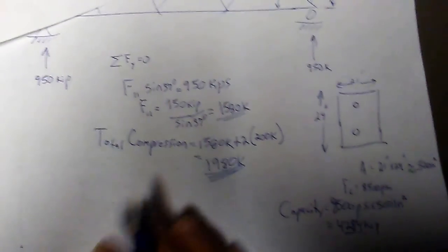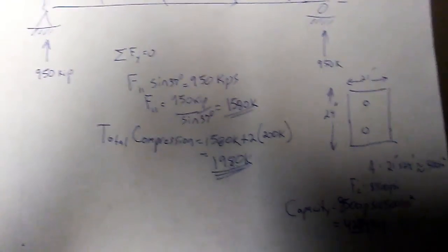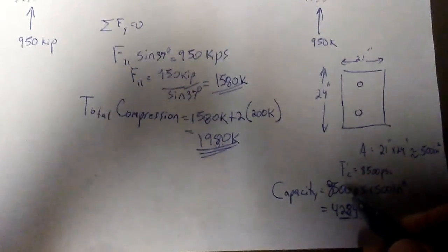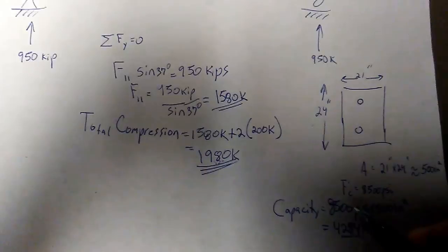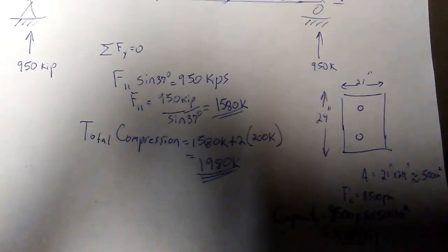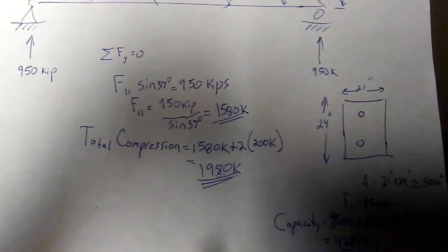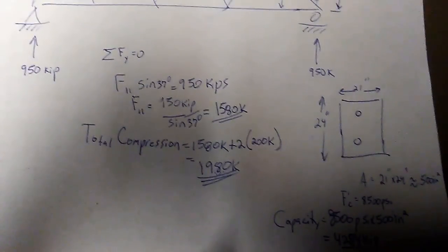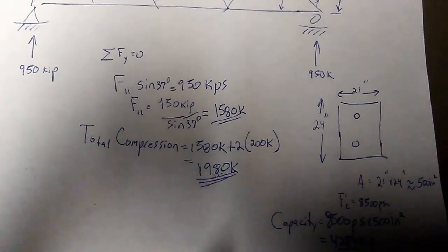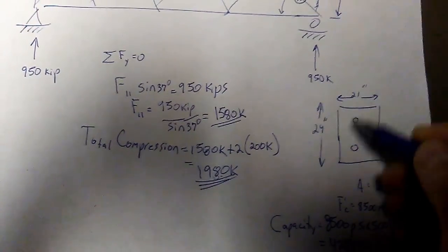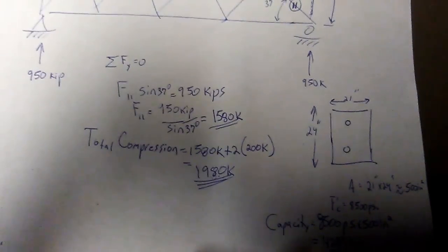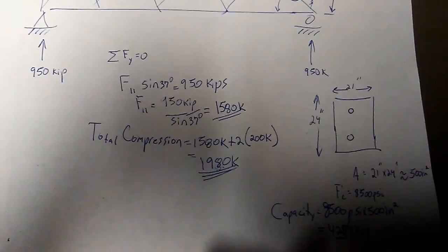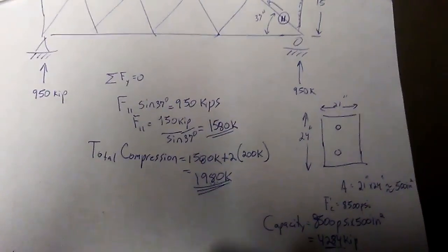There's a factor of safety for the concrete. You actually reduce the strength of the concrete by 15%. Also, because of the rectangular shape of the member, you add another 30% reduction to account for the rectangular shape, and then there's another reduction factor for the possibility of eccentricity, which I discussed in part 2.